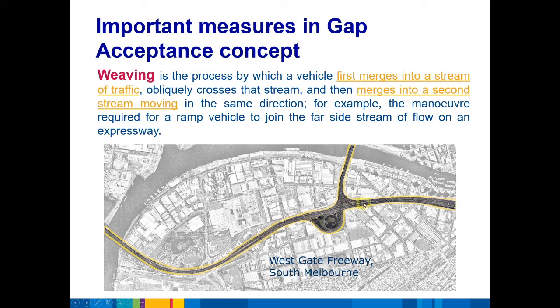There's merging streams, all of this stuff here, and then there's exits to Kingsway, Montague Street, Power Street, or heading to the bridge. And wherever you come in on this route, if you want to get to your destination, you typically have to weave. You have to change lanes in some way in a very busy, congested part of traffic. And again, for anyone who's done this drive, you might have felt somewhat uncomfortable. You don't have a really long length to figure out what lane you need to be in, to get into that lane, to try and pick a gap in traffic when everything's so congested.